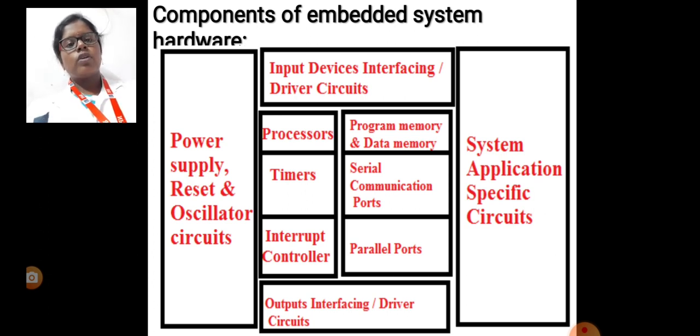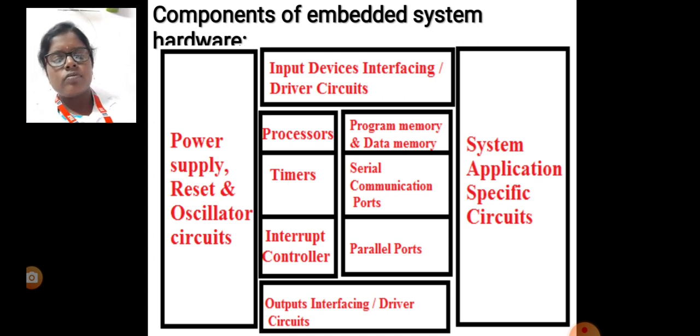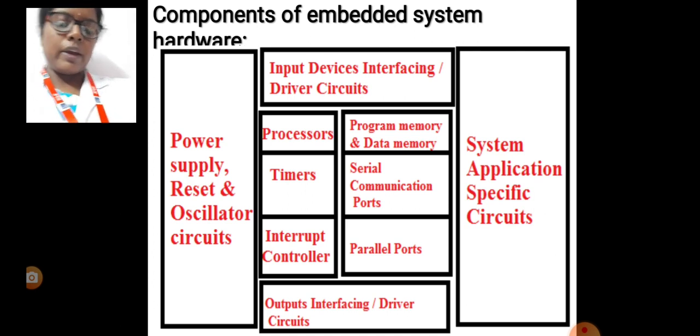Okay, a microcontroller is used when a small embedded system, or a part of an embedded system, has embedded software that has to be located in a single internal memory, and when on chip functional units like an interrupt handler, port, timer, ADC or PWM are needed. Okay, now the various functional circuits in a microcontroller chip.